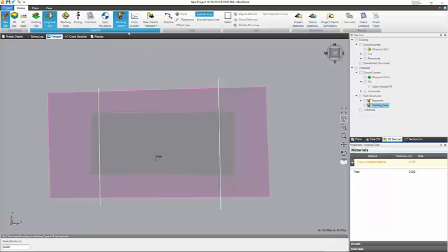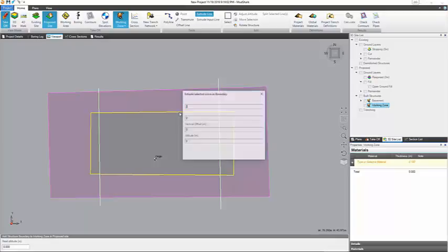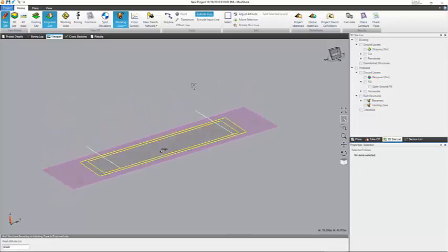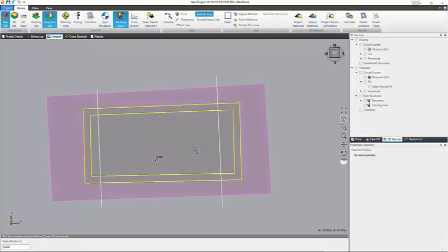So now we want this working zone to be extruded from the edge of this by a certain distance. So we'll click on that and we'll do, say, 1.5 meters out to give us our working zone around the basement area. Let's go OK, and that's created it. So we do that, we can see there.